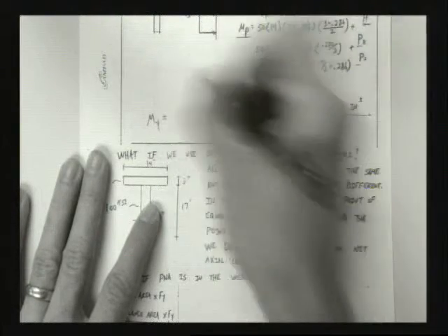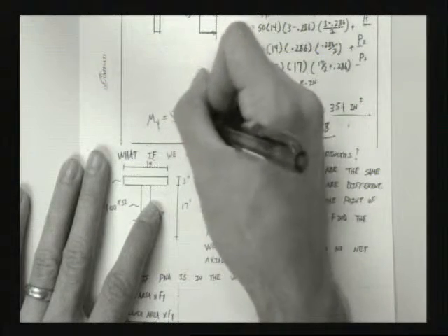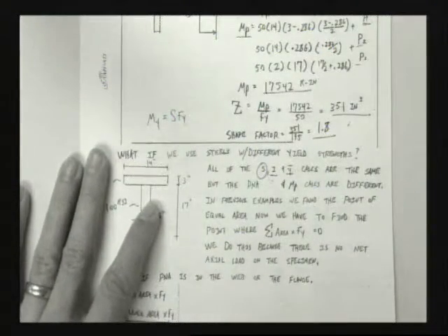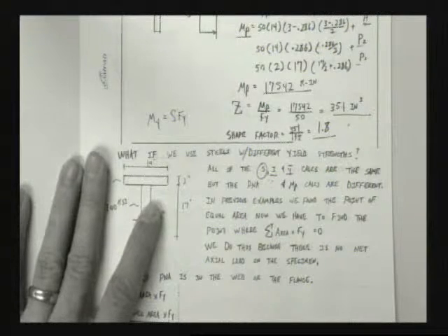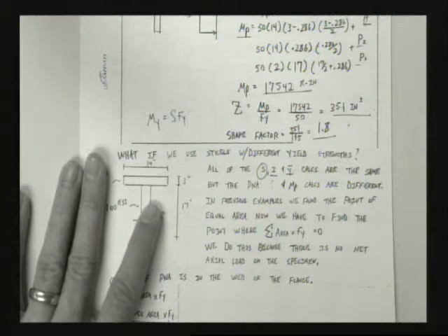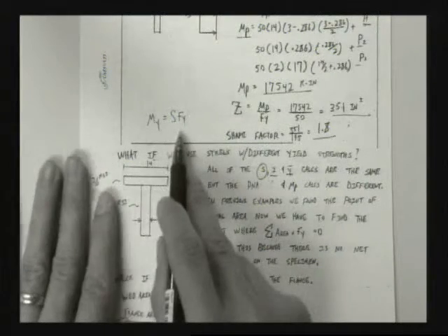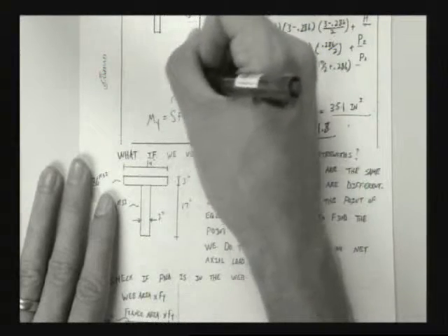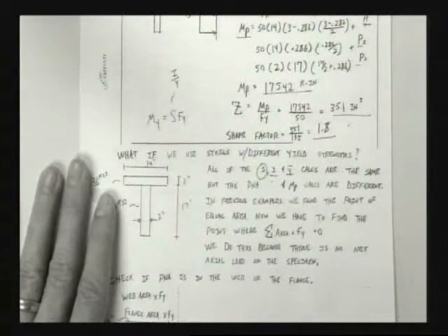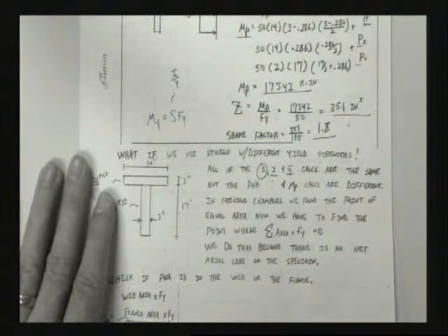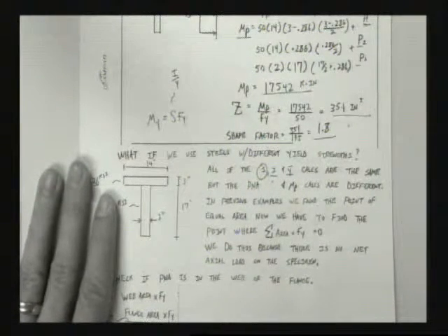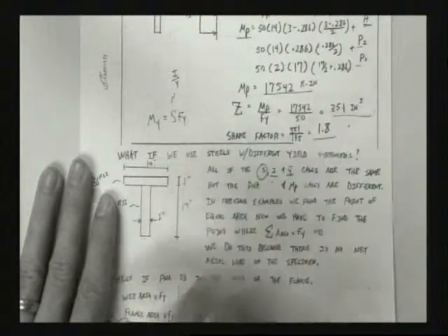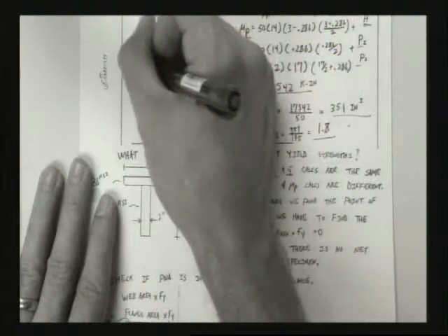That when you think of S, it needs to be, that's the equation: M_y equals S times F_y. And when F_y is constant, then S is truly equal to I over Y. But in this class, it's very possible that I could give you, let's say, an I shape.